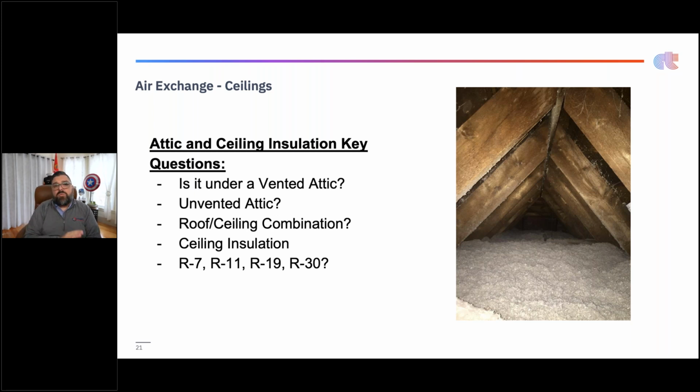And really where I see guys go wrong here is when they have multiple types of insulation. So a lot of times you'll find there's some fiberglass batt insulation in an attic, and then maybe it's air sealed and weatherized, and they blow another 5.5 inches of cellulose on top of the batt insulation. In order to get this number correct, you need the total effective R value of the ceiling. So you need to measure the fiberglass insulation, let's say 6 inches averages out to be like R19. And then 5.5 inches of cellulose will give you another effective R20. The added of the two would be R39 for that ceiling. That's what I have upstairs, all right?